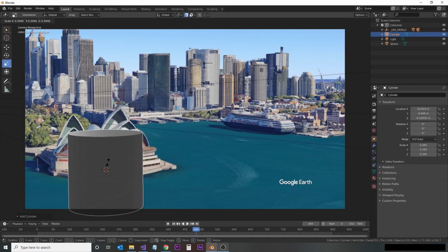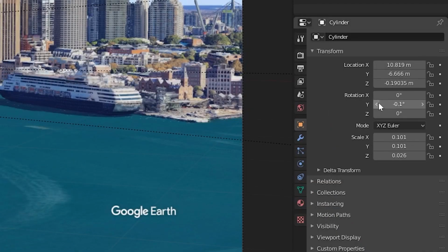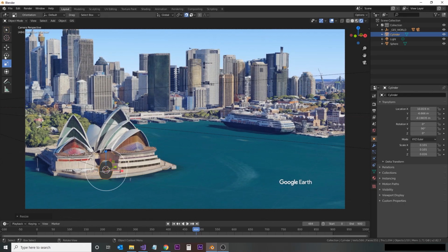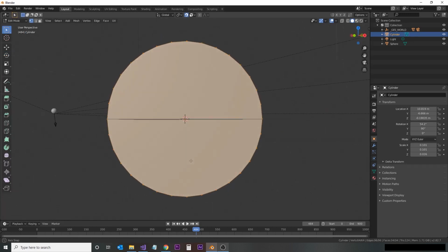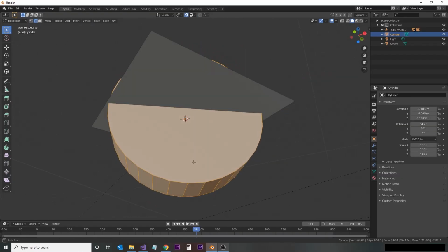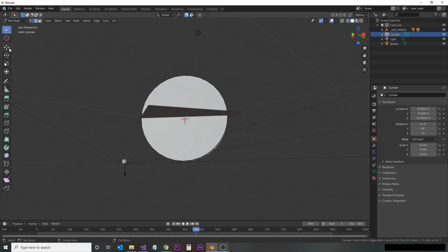I'm going to resize the cylinder. We'll then adjust the y-axis of the object to 90 degrees. And switching to the rotation tool, manually adjust the X rotation. I'll then press the decimal key on the number pad to zoom into the object, and tab to enter edit mode. Using the line selection tool, I'm going to select several lines on the side of the cylinder, and I'll be stretching these out to make a traditional place marker.